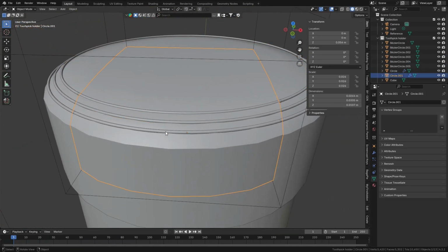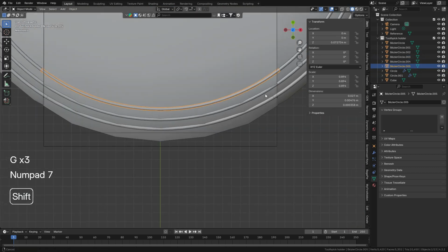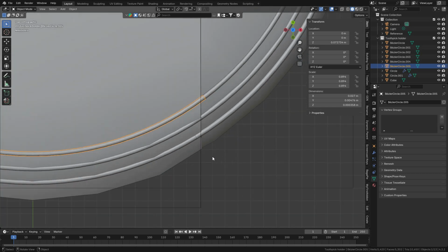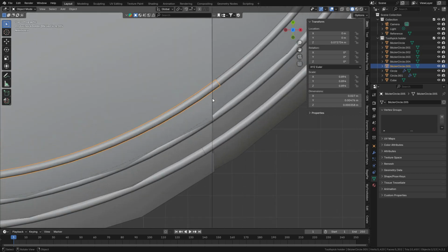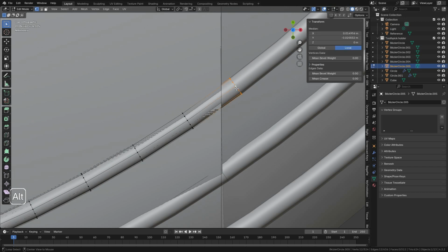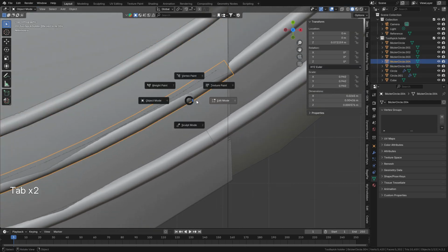And that looks beautiful. So now we have all of these here, which are completely separate from them all. Now before we go on, you want to edit them so they are right along this edge here, where the toothpick cap is, or where the boolean is giving us that line. So select, for example, this first curve, go to edit mode, select this, double tap G on the keyboard, then slide it in along its normal axis. You can press S, then X, 0, enter, then scale it up. So it should just be about there. And do the same to these two as well.